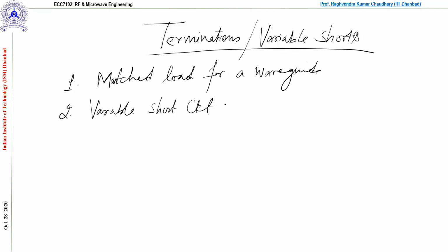So particularly if I talk about the first one, correct. It actually involves like the basic idea, which depends on the lossy wedges, slabs, and the tapered resistive cards. Correct. Means what I'm saying, let's say if I try to make a waveguide kind of thing, I'll try to do these things.